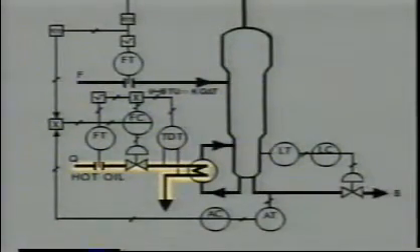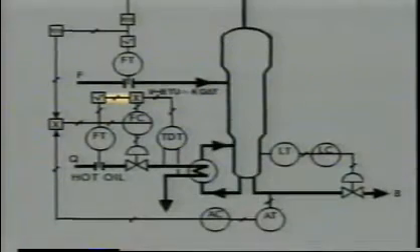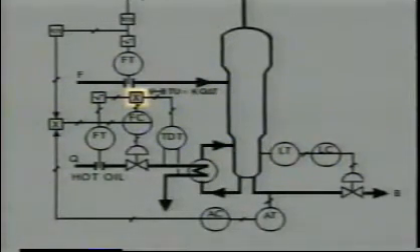This is the hot oil line to the reboiler. This balloon indicates that flow is measured at this point. A signal representing the measured value is sent along an undefined signal line to a square root function. The square root is extracted, and the signal continues to a multiplier function. The linearized signal is then multiplied.